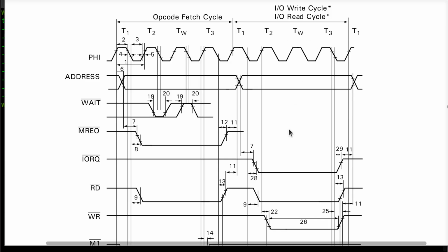So the goal here is to take this asynchronous signal, turn it into a synchronous signal that's phase aligned to phi, such that one and only one active going edge on phi will appear in an enable window that I can use to gate latches and memories and things like that for I/O devices and memory and whatnot.